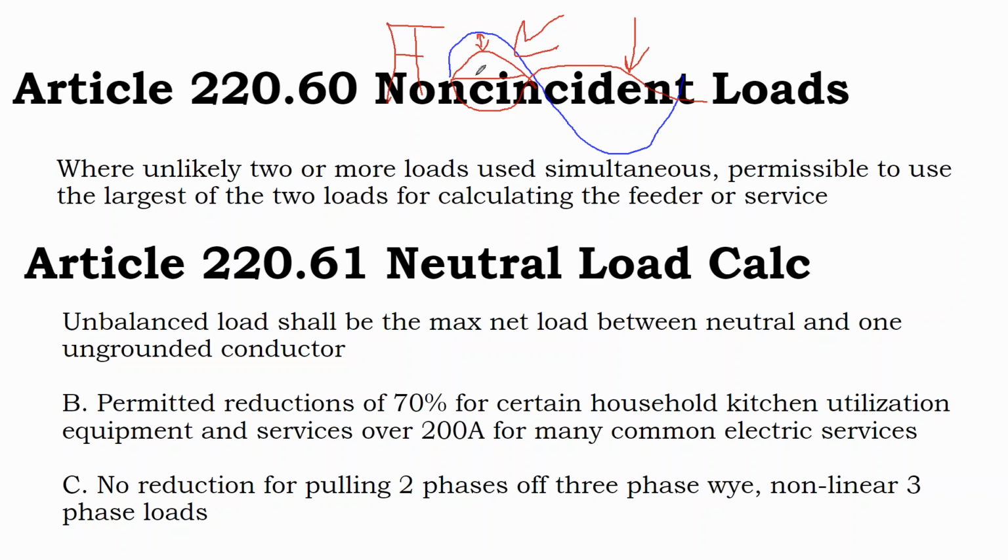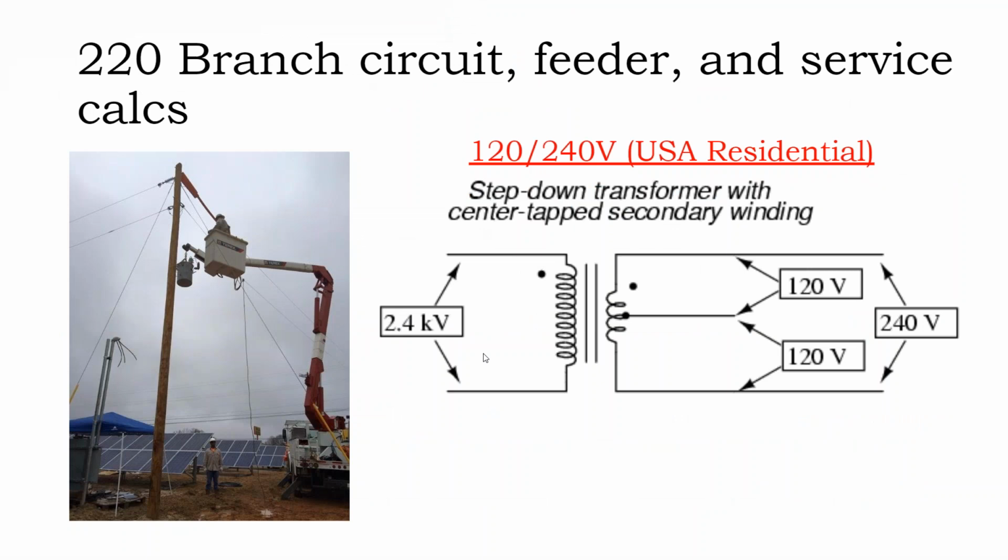So often in this case, it says for kitchen equipment, you can undersize the neutral by 30%. That's kind of, in the solar industry, you usually have the budget for a full-size neutral if you're going to use it, even if you can undersize.